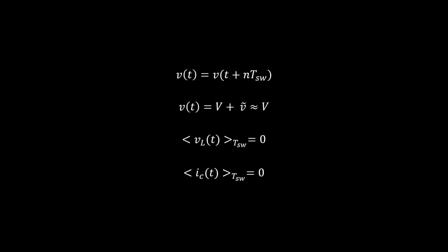So in this lecture, we introduced this idea of steady state, which I've written in this convenient notation where basically point-wise waveforms look identical to each other, cycle to cycle, in steady state operation. The next was this idea of small ripple approximation, where if ripple is small relative to the average value, we can split that signal into a DC component and an AC component and just toss the AC component away, and we end up with the capital letter of the signal you're interested in.